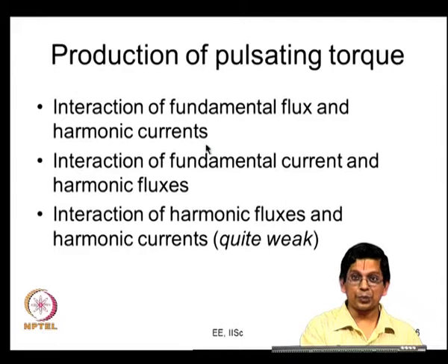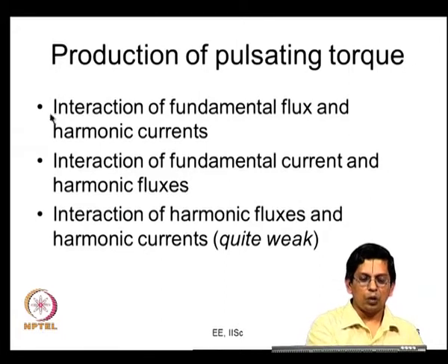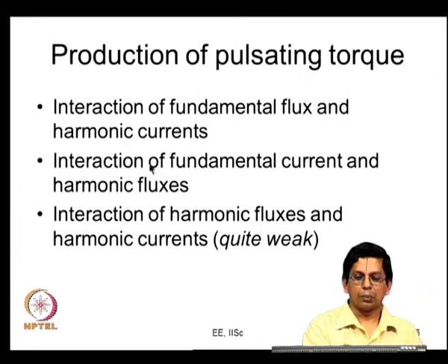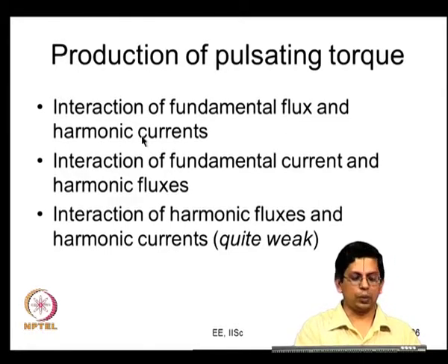If you express the inductances in per unit terms, this leakage inductance is going to be very small. Therefore, the harmonic voltage divided by leakage inductance is going to be bigger, whereas the harmonic voltage divided by the magnetizing inductance is going to be lower. So that is a simple argument to say why this will be more dominant than that. Both could be considered, but normally this is the more predominant term that you would look at.